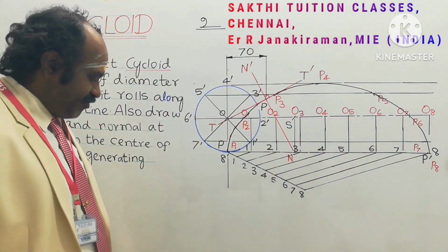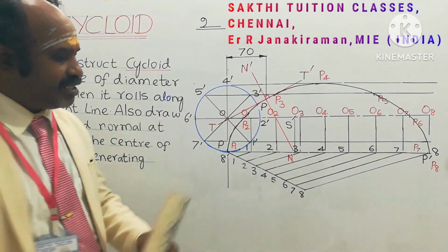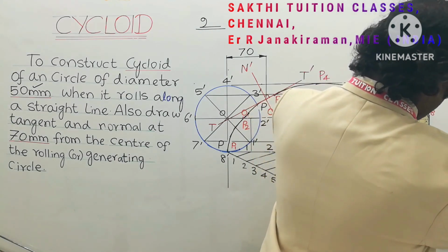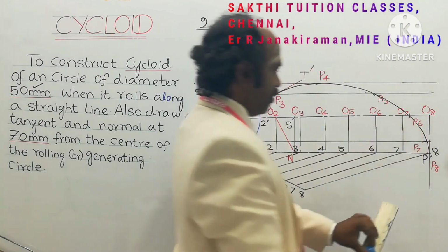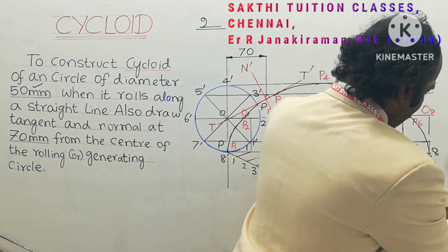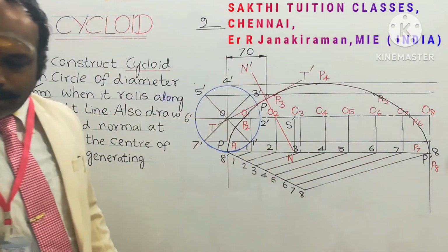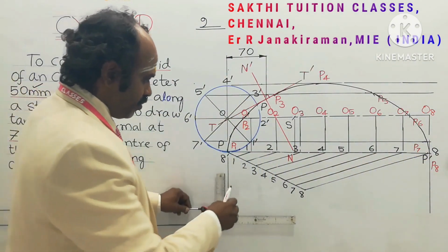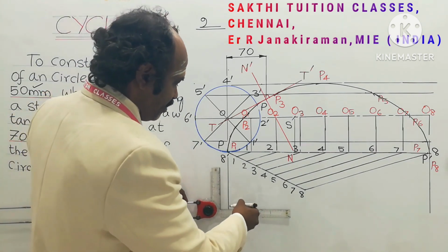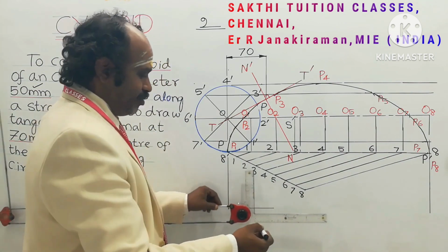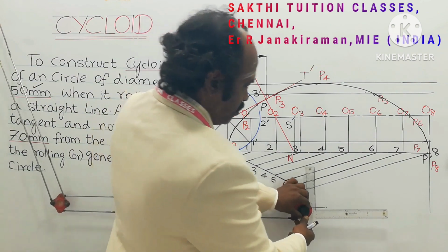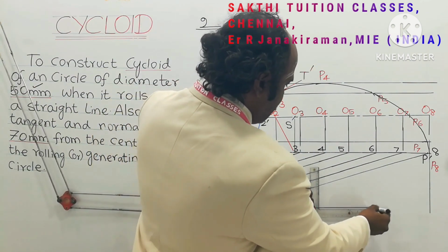The drafter scale does not have sufficient length, so let me use a freehand scale. But this should be a perfectly perpendicular vertical line, drawn like this. Using the vertical scale of the drafter, this vertical line, called the extension line, shall be drawn. The circumference of the circle is taken as 157 mm, that is the perimeter of the circle. Draw one dimension line using an HB pencil like this. It is called a dimension line, a thin line drawn using an HB pencil.